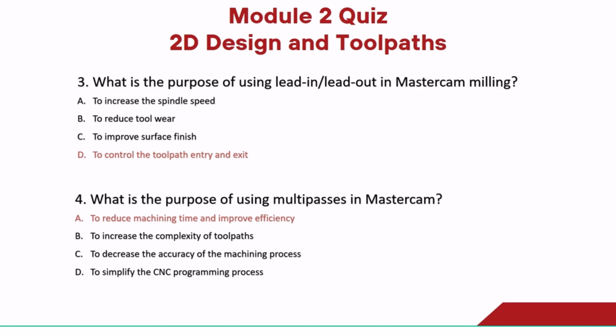The purpose of multi-passes is to get the toolpath to increase the efficiency, give more surface finish to the workpiece, and increase the cutting tool life also. It gives a smoother and shinier surface to the part. So that's why we use the multi-passes operation in MasterCAM.